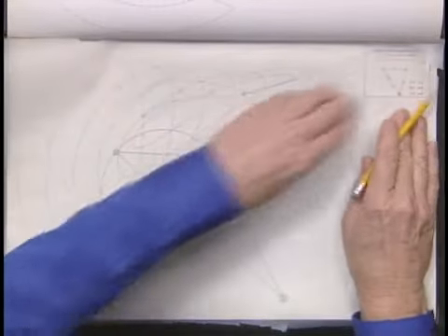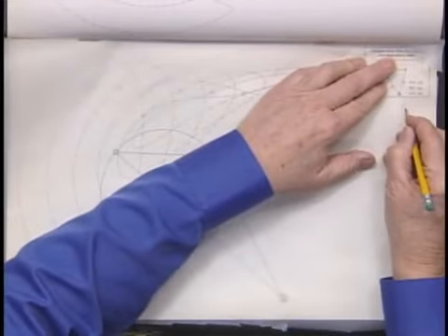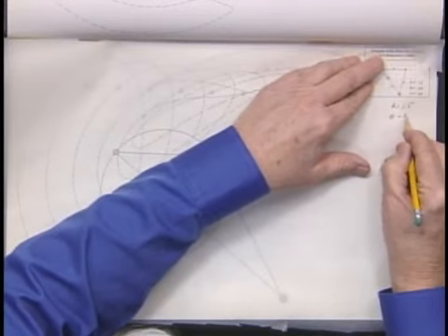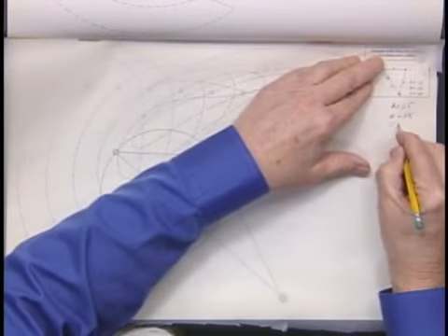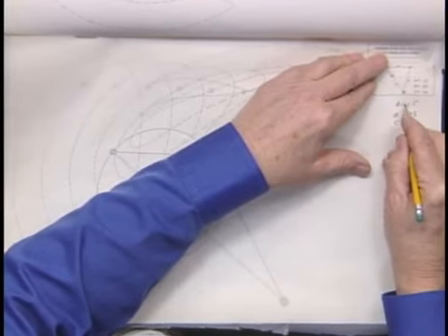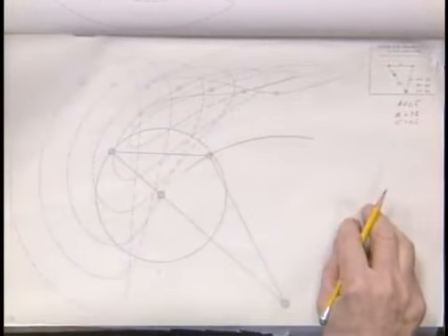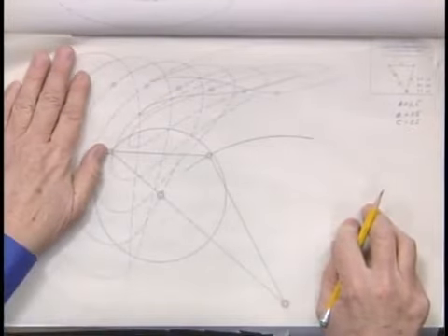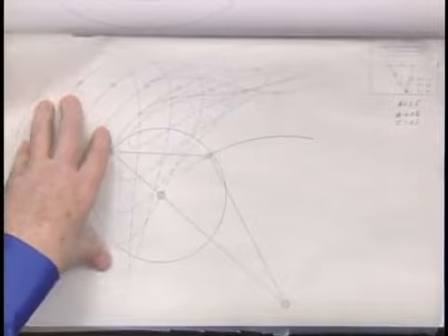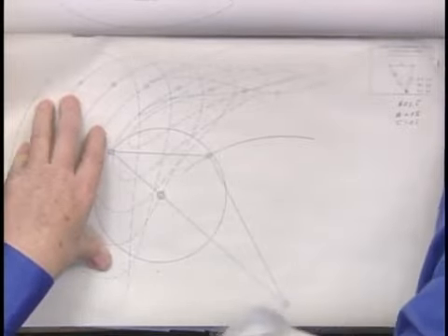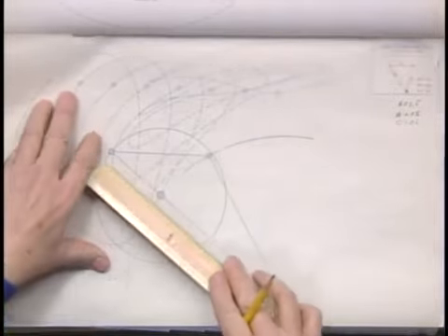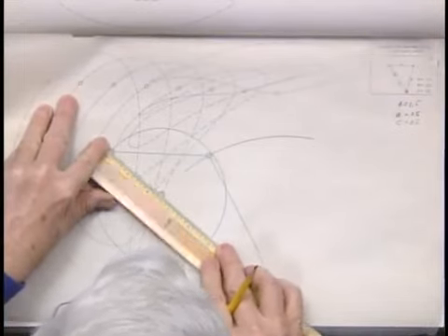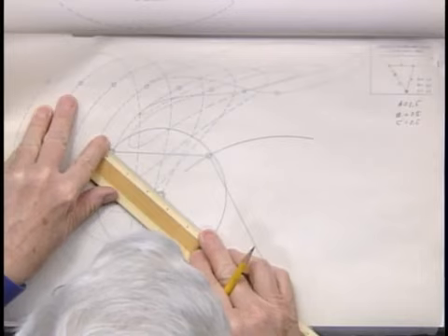Now, I look up on the upper corner here. You can't see it. We won't bother to zoom in, but I'll tell you, A is 1.5, and B is 2.5, and C is 2.5. So I know already the dimensions of my links, and I can let my crank be any value I want. It can be 10 inches, it can be 2 inches, it can be 75 millimeters, whatever I feel like. In fact, if I put my scale on this drawing in the book, I find that it's pretty close to 2.5 inches.